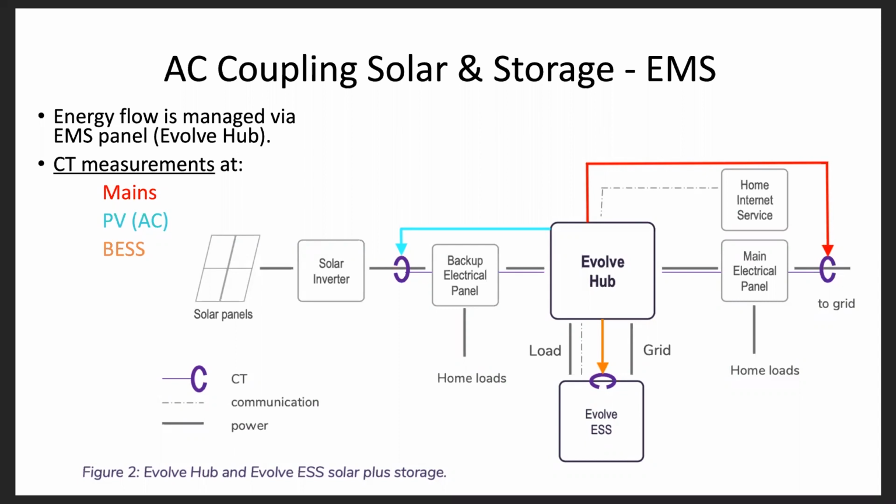Is Eguana planning to develop and sell an off-grid version of our products? Simply put, no. We specialize in grid-tied battery energy storage systems. They will work in a backup or islanded mode, and they would essentially work for an off-grid only system, but some of the features that are built into it, like auto recovery, are not going to be available because there's no grid voltage.